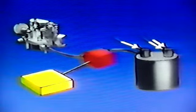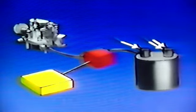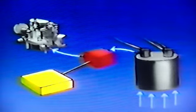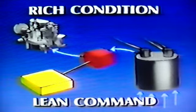When the engine is warm and in closed loop operation, the ECM sends a signal to turn the purge valve on, drawing air up through the bottom of the canister and sending fuel vapors back into the engine. The oxygen sensor then reads this rich condition, and the ECM sends a lean command to the carburetor to balance the air-fuel ratio. There are some engines which don't use a computer-controlled canister purge valve, but even these are set to operate above closed-loop temperature levels and use a thermostatic vacuum switch that functions on coolant temperature.